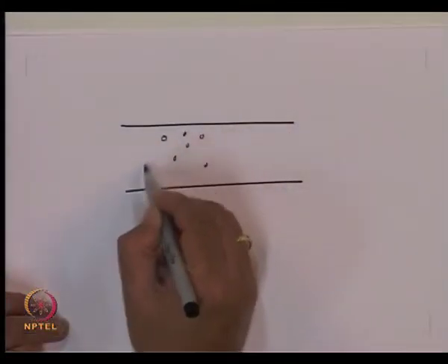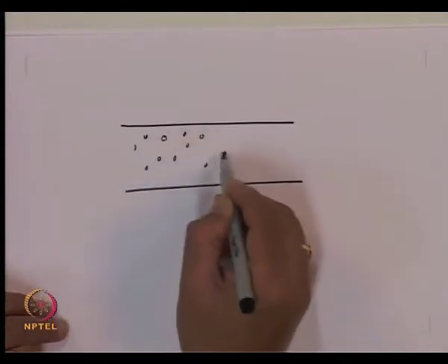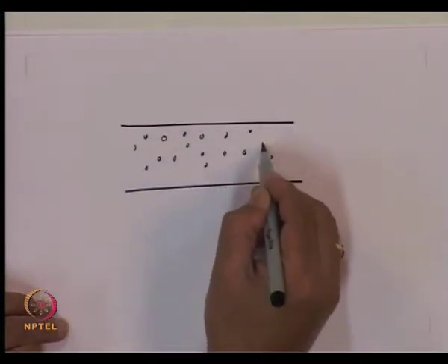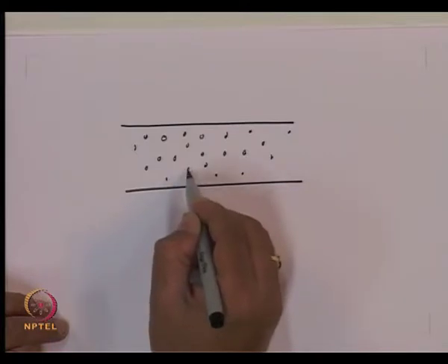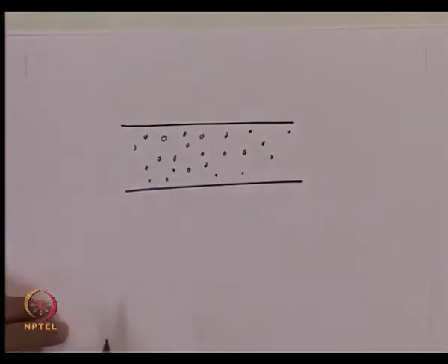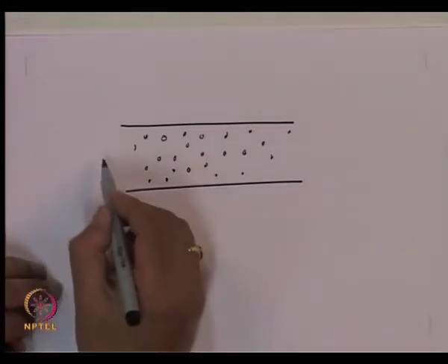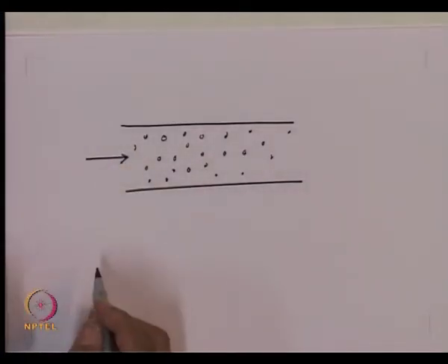In other words, we have some kind of regions which are created inside the optical fiber, which are distributed all through its length, and these sizes are very, very small, a fraction of a micron. So, when the light tries to propagate through this, it sees a small perturbation in the refractive index.